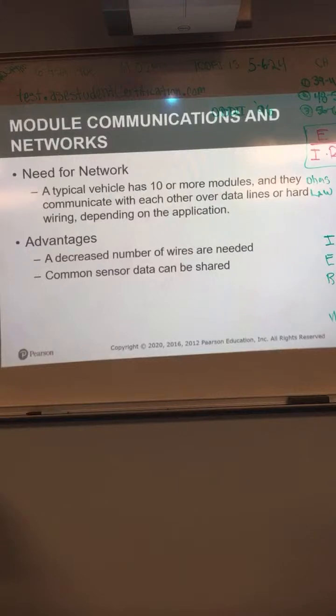Why do you need network communications? Because cars have lots of computers on them. Is that in this chapter, or are you just asking to see if we remembered? That's not going to be in this chapter. I'm just telling you because of the way this chapter is structured for OBD2 communications, okay? You're not going to need to know that, but it's a good idea to know that. That way, if you're working on a car 95 or older, you know that you can't use that scan tool. It won't work. Gotcha. It's got to be 96 or newer.